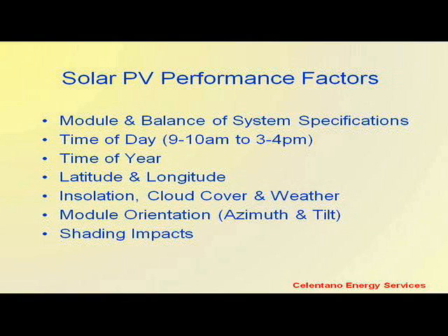Your insolation: is there going to be a lot of cloud cover that is blocking sun from reaching your panel? The orientation of your panel: is it going to track the sun? Is it going to follow the sun? Or will it be stationary, always facing south, or is it facing away from south? Shading impacts. Do you have trees nearby?